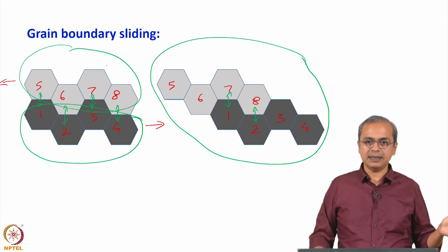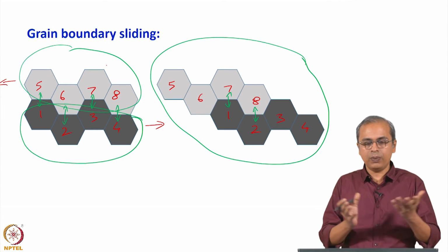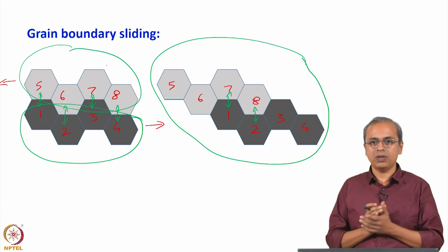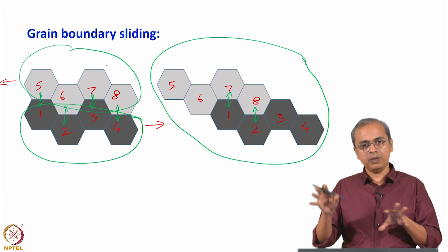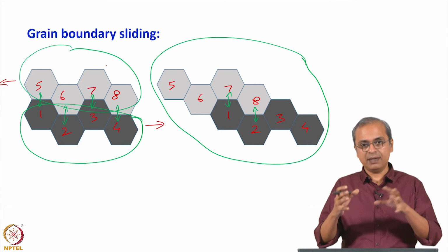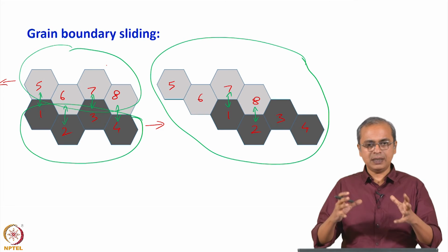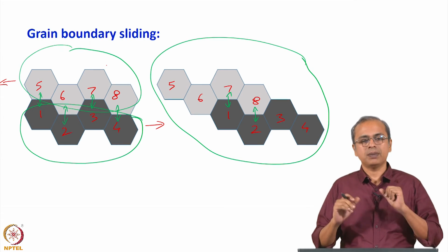There is going to be some grain size variation, and they are not necessarily going to be equiaxed in all directions. You will have a grain which is slightly longer in one direction, slightly longer in another direction, different sizes, and those different sizes are also going to be mixed. You will have like 2-3 small grains, 2-3 big grains, relatively speaking, and they are all going to be next to each other. So it is a kind of a complex situation that you have there, which you are trying to simplify in some sense and come up with a model.